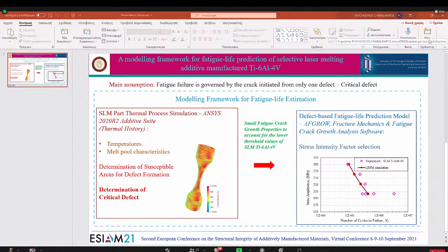And I also think it might depend on the surface finish. For a machined and polished sample, again, I could see that. In the present study, the reference case, the experimental specimen was polished, so there is no surface roughness effect on fatigue properties. Okay.